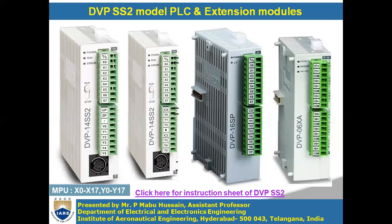So in such a case, you have to add some more inputs to your main PLC. Okay, so for that purpose you will use the extension modules. Okay, this is the digital extension module, and this one is the analog extension module. So here this is also DVP series 16SP. Now here 16 represents the total number of inputs and outputs.